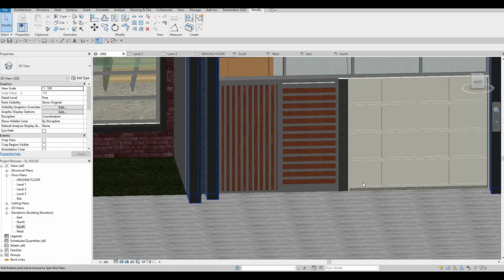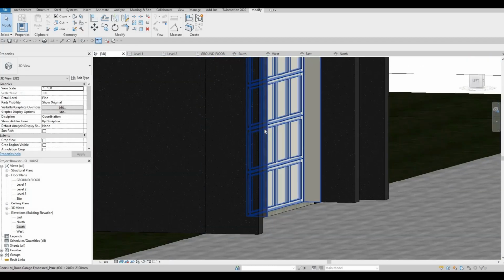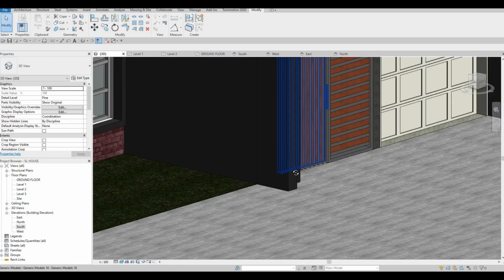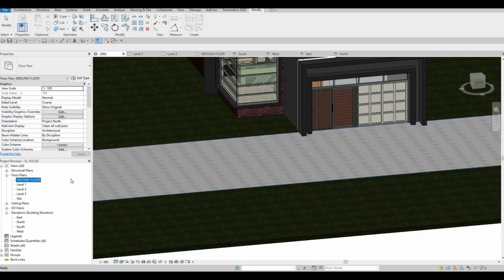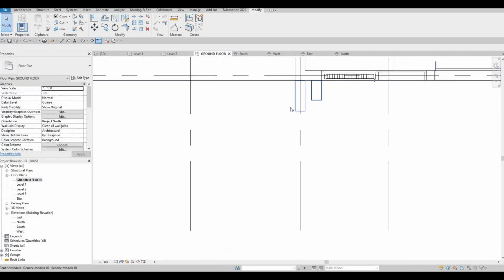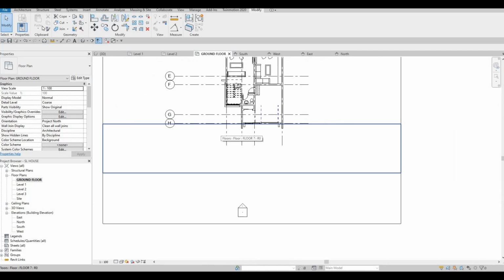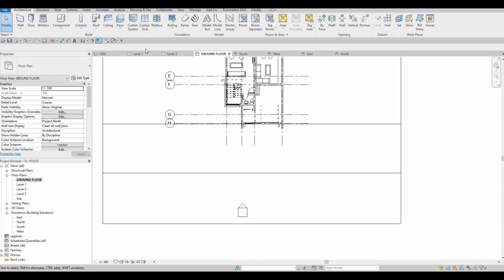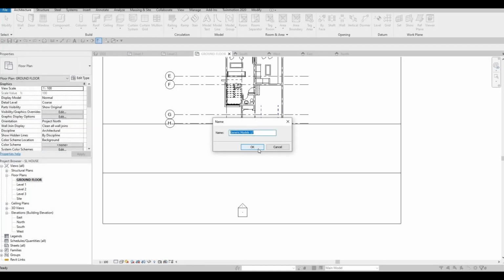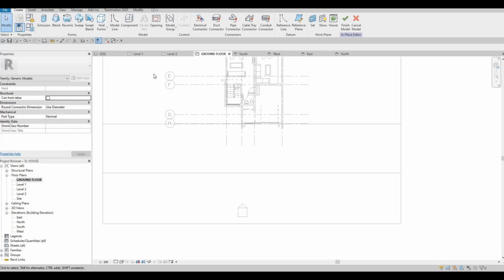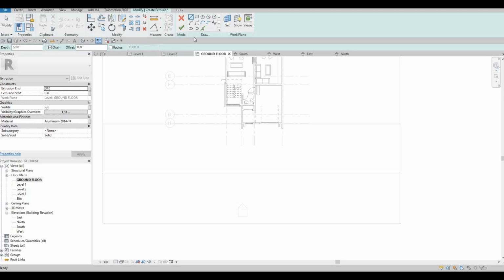And that looks really good. A simple handle, and then we just did it right here. Very fast to do. Now let's go back to floor. And then here what we're gonna do is we're going to add some sidewalk. So we're gonna use model in place again, and then generic model. We're gonna do it on the same, and then here let's do extrusion.